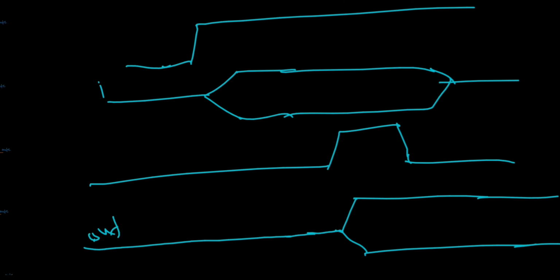So you see, this is out, this is I, this is En, and this is the Cl. The out was already 0, so it just has the 0. When I goes to some value, the out value wouldn't change. You see, it still is 0 because the condition of out changing with the input is when both Cl and En are equal to 1.